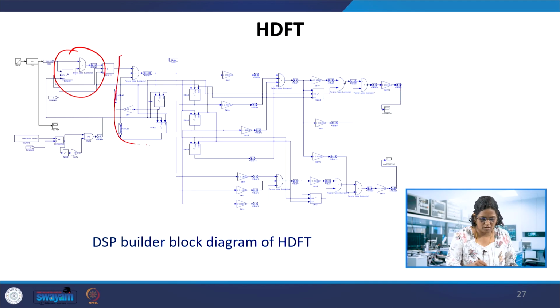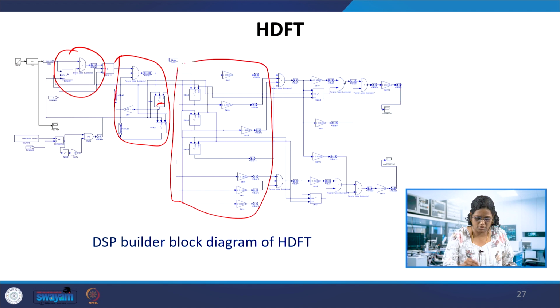And we have this resonator block, where this is L, if you recall, L equal to 4 we have used. This is the portion which has the x of n sample and x of n minus N sample to be removed and x of n should be added. That is, this is implementing the update vector transform, UVT. You can see the multiplications of the twiddle factors we used in the L equal to 4 block. If you just compare this with the Simulink block which we had done, this would tally, and you can easily figure out what these are.